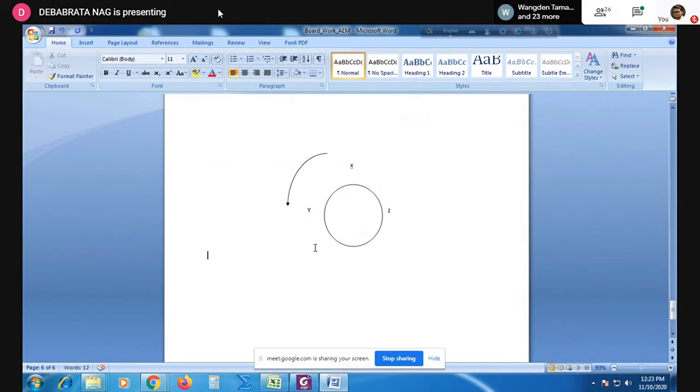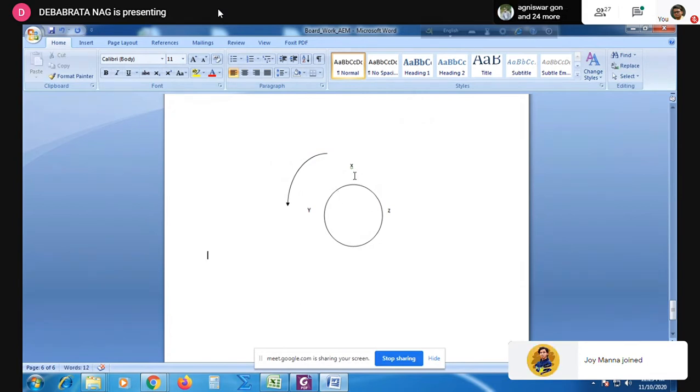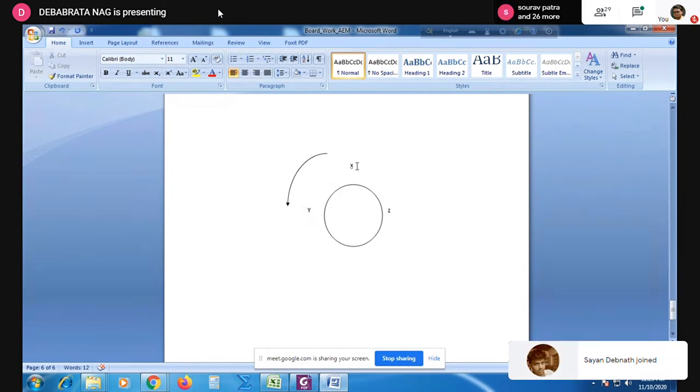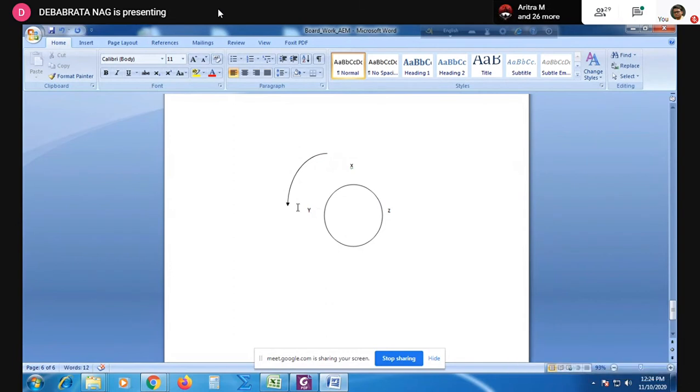So in this case, you see your left hand side, that is this equation. If the x-axis is the axis of rotation, the first equation is pretty simple. Summation fx is equal to Ixx into omega dot x, right? Then what will be your next equation? So if you go this way, it will be summation my, and summation my will have two parts. One is the acceleration part, another is the square of the angular velocity part.